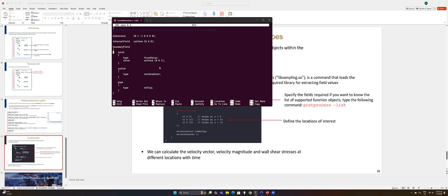And then the other one, front and back, should be pipe, because that's the name we've given to those boundaries. Please note, if you have different names for your boundaries in your case files, you should make sure that the names match. Otherwise, OpenFOAM cannot find them.